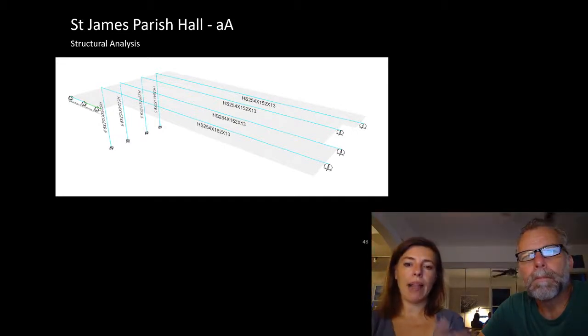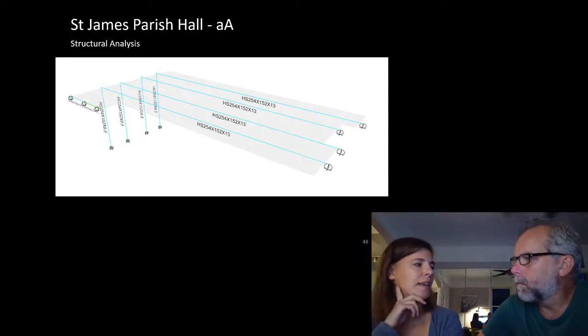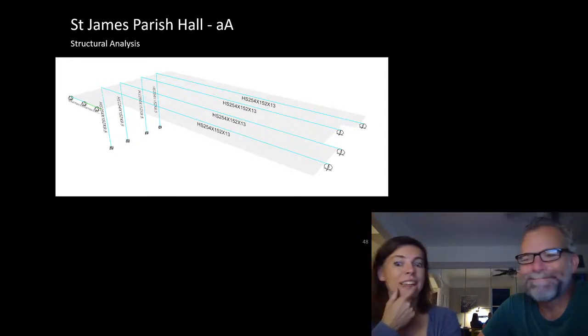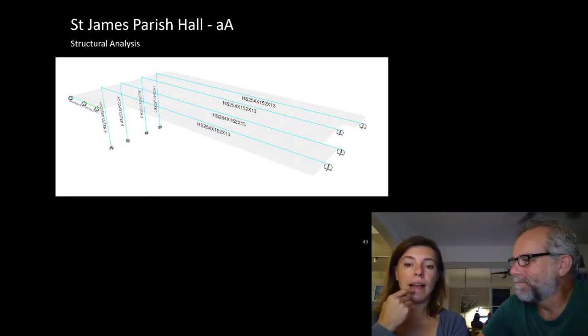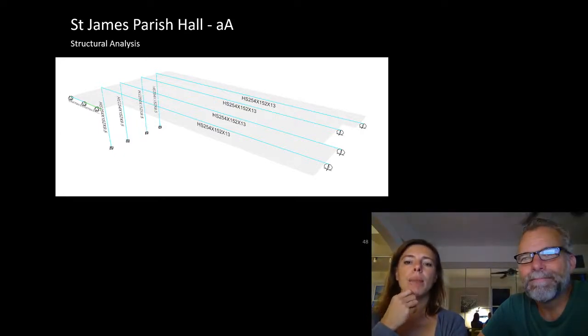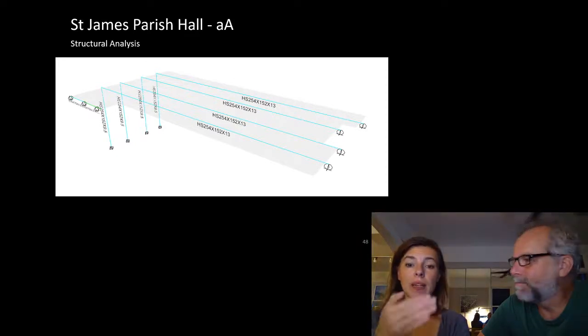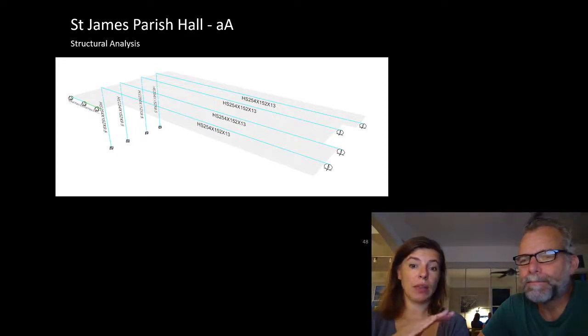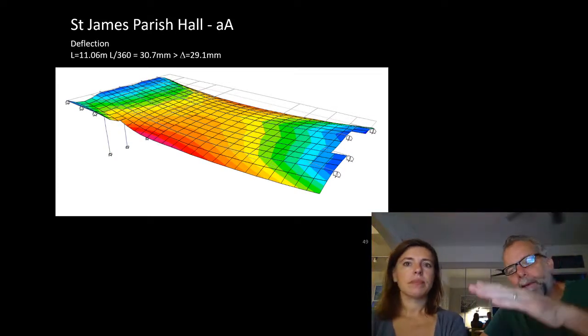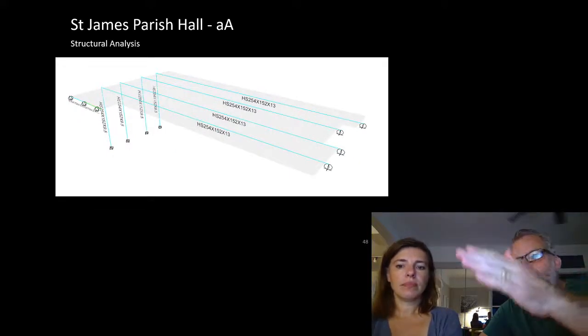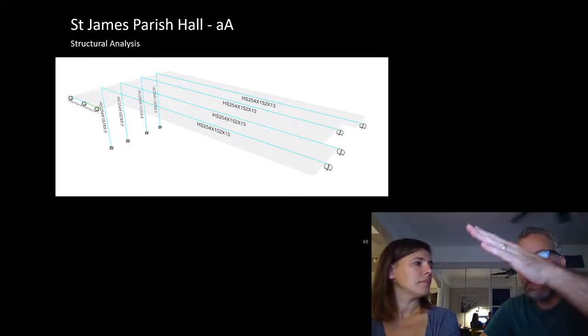We're picking up glass plates. When I went back and looked at this, I was kind of like, oh, I feel like maybe I would have done an even tighter deflection requirement because it's glass. But this was about talking through exactly where the glass seams were going to be to allow that deflection, and the fabricator of the glass was okay with the deflection. Now, just to be clear, glass can tolerate an awful lot of movement out of plane.